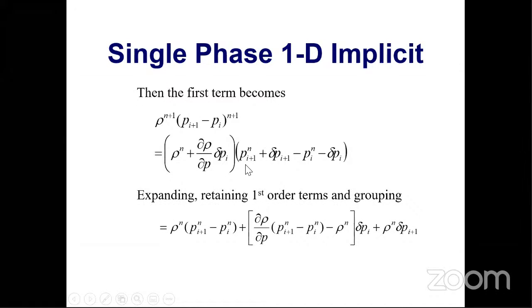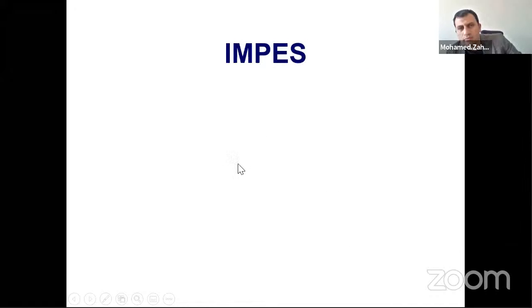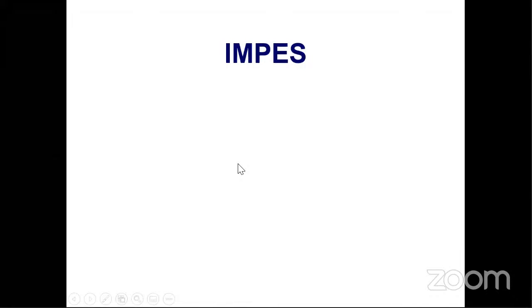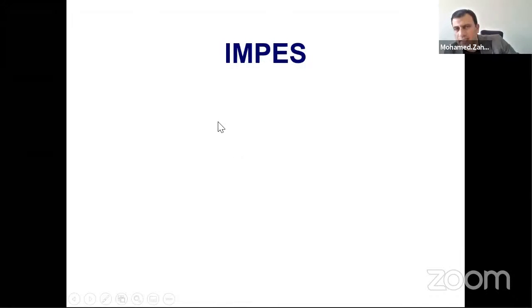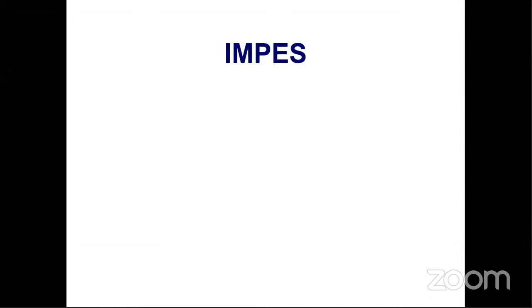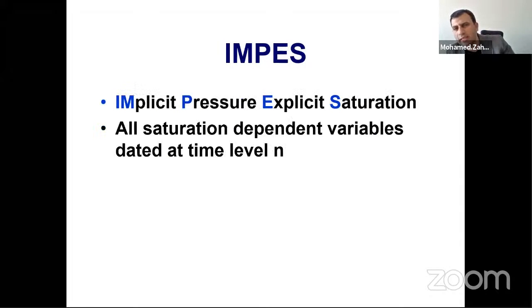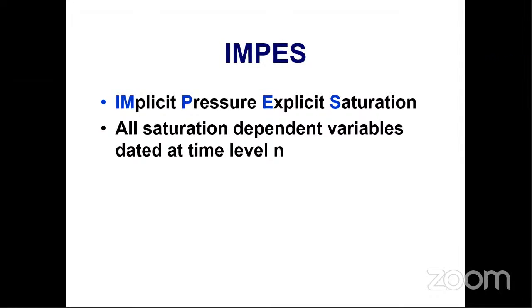And so on, I will not take you through it all. And if you calculate the pressure at the next time step after 1 month, and the fluid property depends on the pressure at the next time step, we call it implicit pressure. And explicit means that you are calculating at the time of now, with the factors of now.